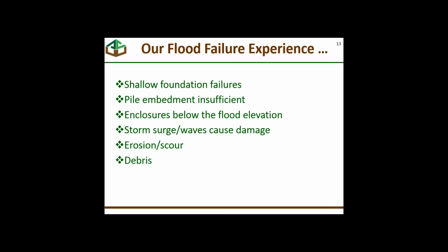Some of those failures have been for really pretty big buildings, multi-story condo or apartment buildings built right on the water at a time when the flood maps for that area allowed shallow foundations, and then a storm comes along, knocks the building down. And it knocks the building down by eroding underneath the foundation and causing a foundation and a building collapse. So that is primarily how shallow foundation failures occur, is using the wrong foundation system for the hazard that is actually in play.